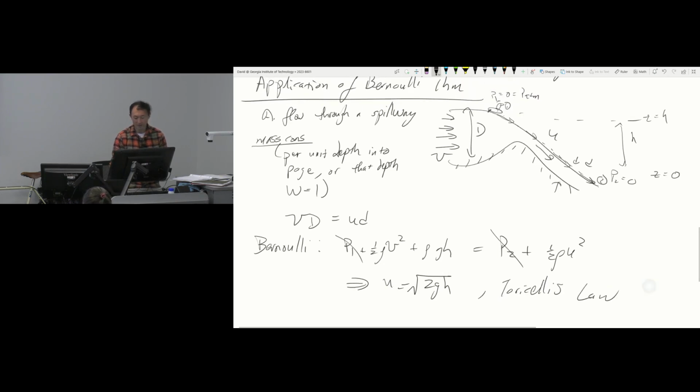So notice a couple things physically. That lake on the left, on the top of the mountain, the amount of water in that lake didn't actually affect the flow speed. Bernoulli's equation is the equation between 2 points, and it says that your velocities only depend, in this case, on the height differences. So I could have that lake being like a mile wide or just a few inches wide. I essentially have fluid flowing downhill.